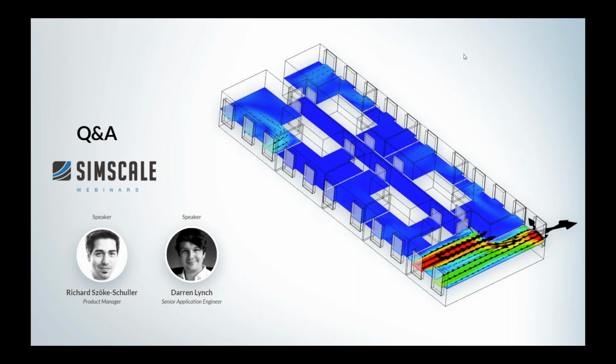Yeah, I guess there are a few key concepts for COVID mitigation, which we maybe all have meanwhile learned. It's all about air exchange rate and reducing regions within the classrooms where we have long standing air. And this is exactly what you can do with SimScale, what we've seen before. So we can efficiently analyze and assess air exchange rates, mean age of air within the rooms, and use this information to actually find different types of ventilation options that provide a higher air exchange rate under different circumstances,